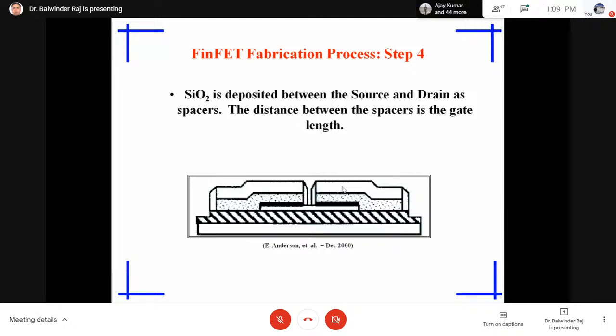and the fabrication cost keeps on increasing. But the fabrication cost is less with silicon dioxide, but we have a challenge in terms of its low dielectric constant, so its leakage current might be high. So if we have to go for low leakage, low power dissipation, we go for the silicon nitride. And also the benefit is silicon nitride can tolerate more temperature as compared to silicon dioxide.